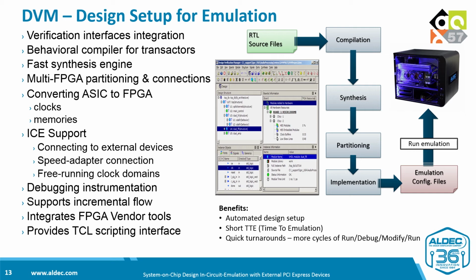Another important part of emulation is hardware debugging. During design setup, the DVM tool provides source code instrumentation to preserve all required design internal signals and integrates the design with debugging infrastructure or the memory debug ports.